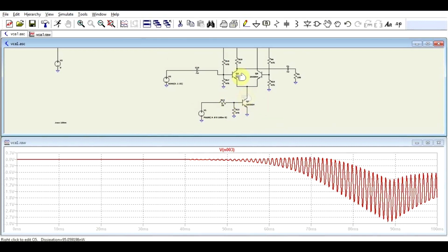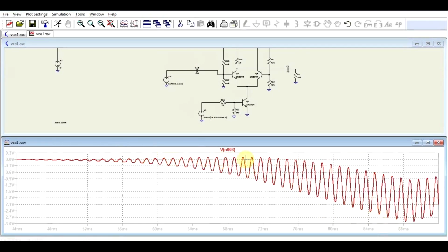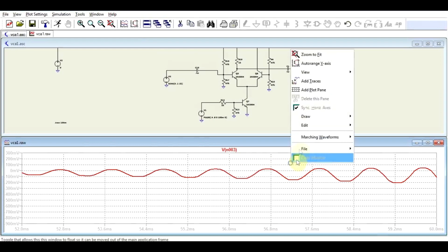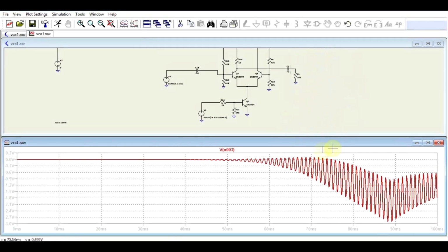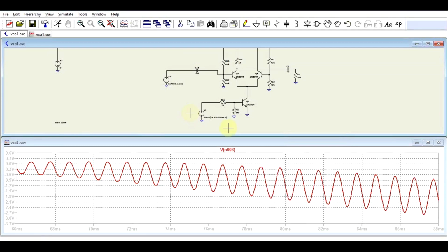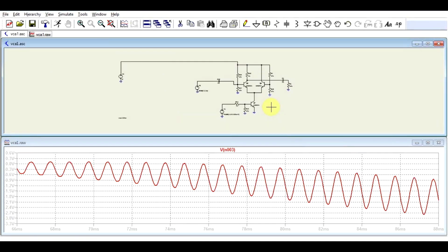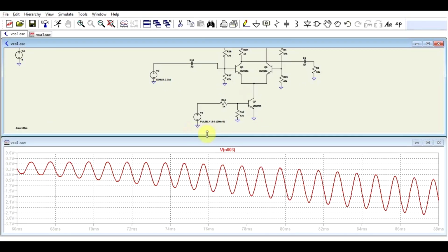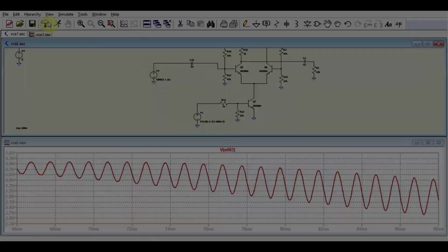So by controlling the current going through the two arms of the comparator, I can vary the amplitude of the output signal. And the good thing about it is that there's minimal distortion. Even when the signal is with a very low amplitude, there is some distortion, but it's quite small. And afterwards, the signal is almost unaffected. Only its amplitude is varied. Now, of course, there are better, much more complicated ways of doing this circuit, but this circuit is good enough. So now let's see where we get this volume control signal.